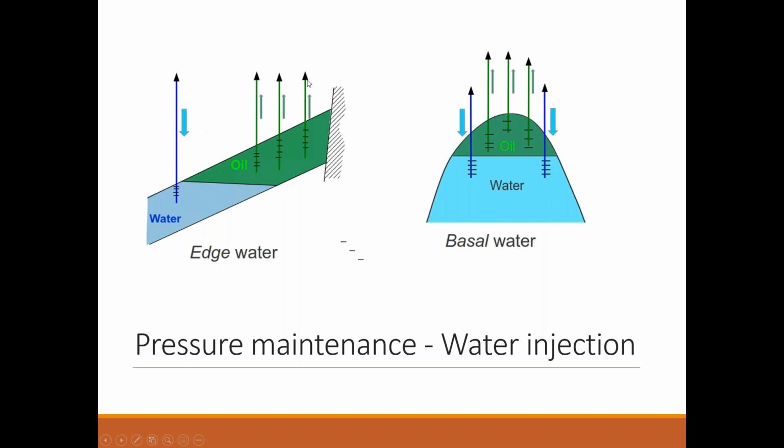Let's suppose you want to convert this particular well into a water injection well; that is not possible. But in a bottom water drive reservoir, there is flexibility. So this well can be converted to a water injection well, but this well cannot be converted. In an edge water drive reservoir, there are typical characteristics.